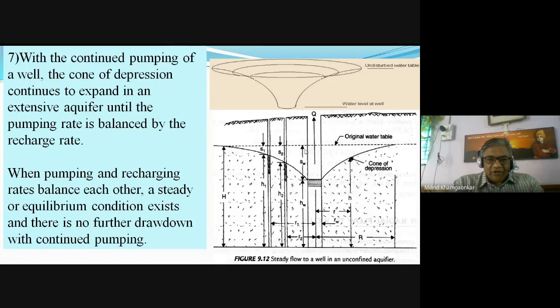The radius of influence will be small. But as the water level goes below and below, the radius of influence will go on increasing. With the increase in the depression head, this cone of depression will go on increasing till the pumping rate is balanced by the recharge rate.